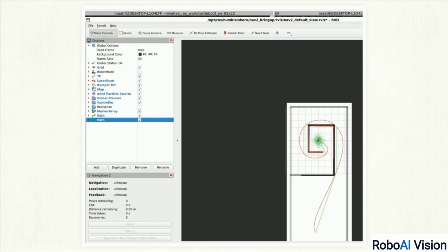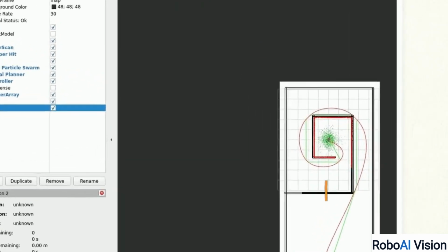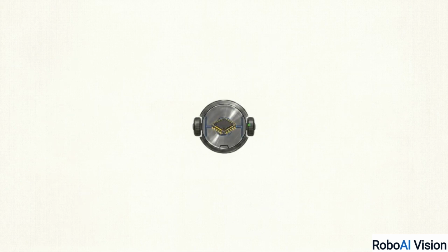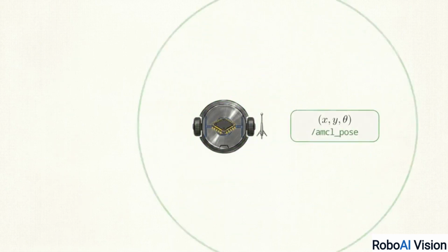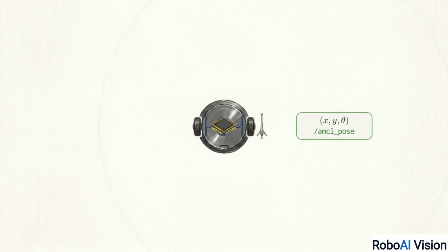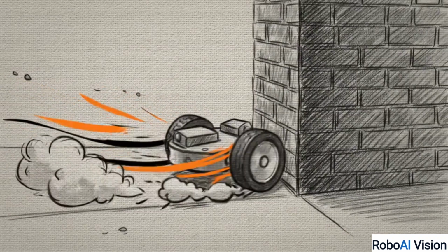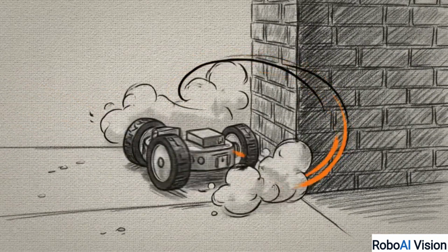This view in RViz shows the result. The green AMCL particle swarm appears immediately around the robot's footprint. You can watch the particles converge, snapping together as the algorithm confirms the robot's position. This dense cluster is the visual confirmation that the filter has successfully synchronized the sensor data with the map. With the position confirmed, the AMCL node begins broadcasting continuous coordinate data to the /amcl_pose topic. With localization isolated and the pose verified, our custom A-star planners and controllers can use this data to take command of the robot.